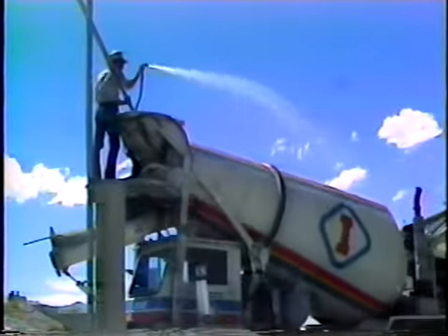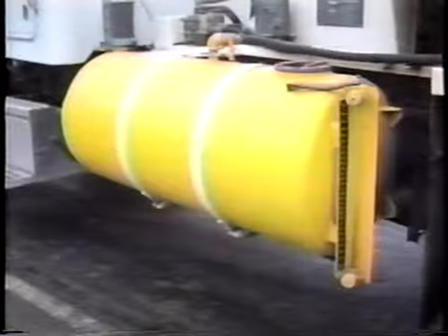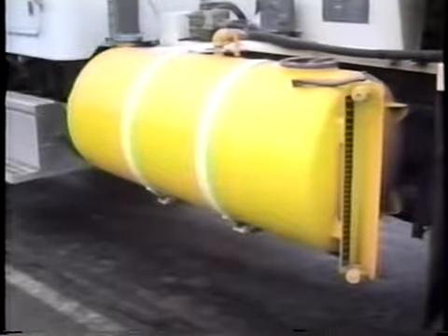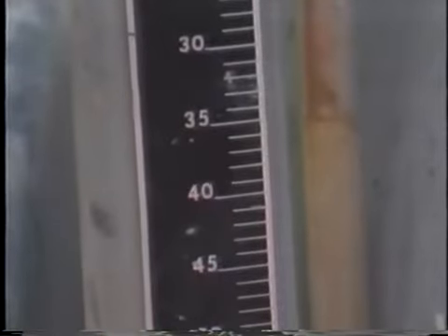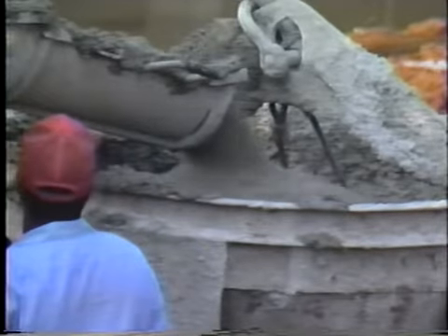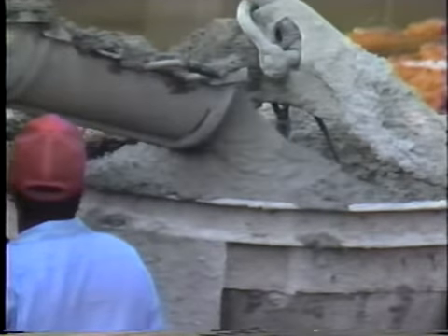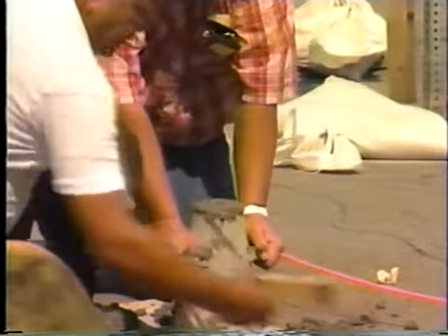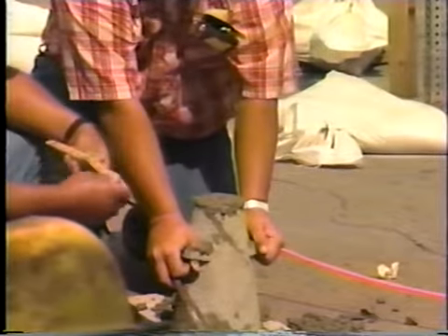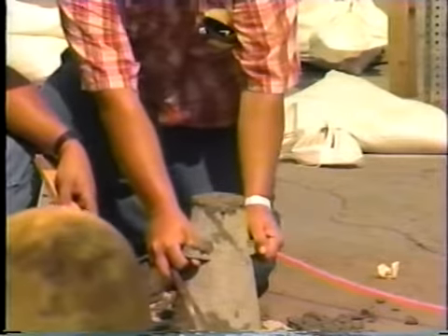For example, if wash water was left in the truck before it was loaded, the mix may be too wet. Or the truck driver may decide to add water if the mix begins to stiffen. So it's important and it's required that the quality of the concrete be verified before the concrete is cast. Verification is provided by conventional controlled tests performed in the field.